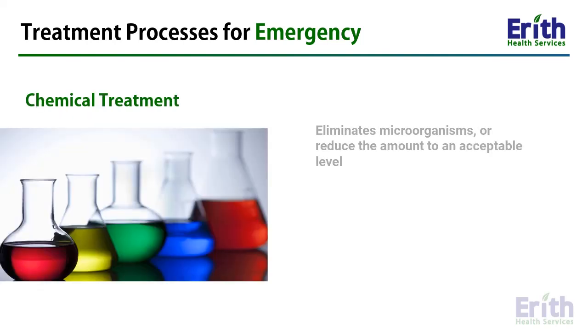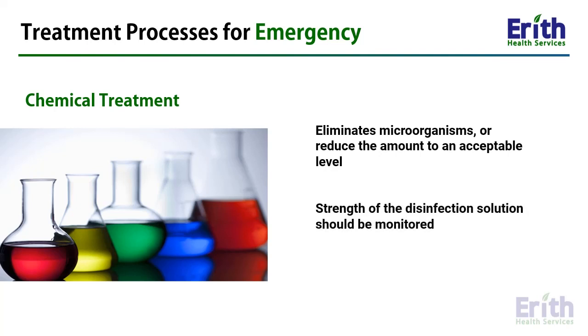Chemical treatment eliminates microorganisms or reduces the amount to an acceptable level. Microbial inactivation tests are important to ensure that concentration and exposure time are sufficient. Since many disinfectant solutions lose their ability to destroy pathogens with time and organic load, the strength of the disinfection solution should be monitored. Many chemical disinfectants are themselves hazardous and toxic, so proper precautions should be exercised and PPEs worn for safety. Wastewater discharge should also be monitored.